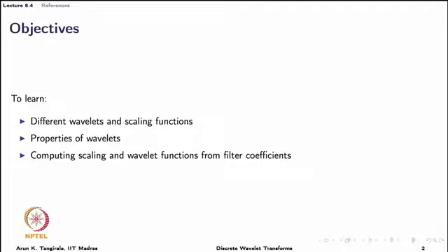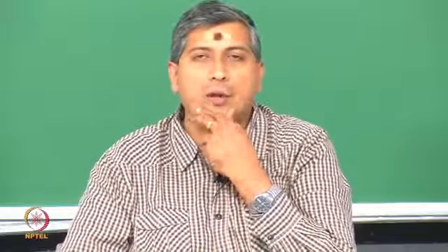functions from filter coefficients. Remember, we have said that as far as computation of DWT is concerned, both decomposition and reconstruction, one does not need the scaling functions or the wavelets, but still it is a useful exercise to learn how to derive these functions, how they look, what these basis functions look like, because what we need to do eventually is to select a wavelet for a particular analysis or a scaling function, and in selecting a particular family of wavelets we would like to know what features these basis functions have, and unless we look at these functions in time, that is their shapes, we will not be able to make much of